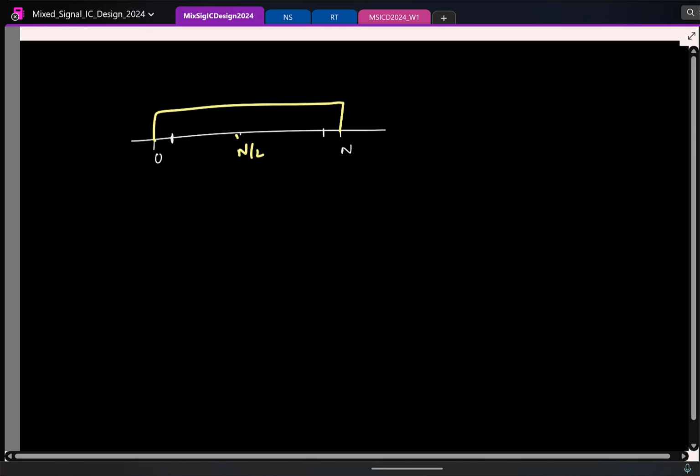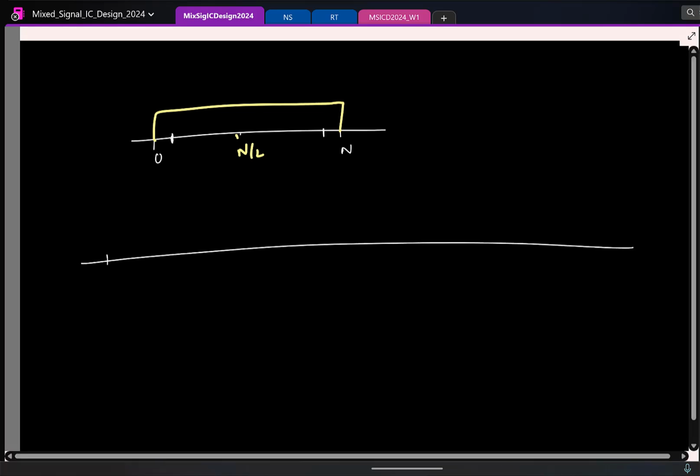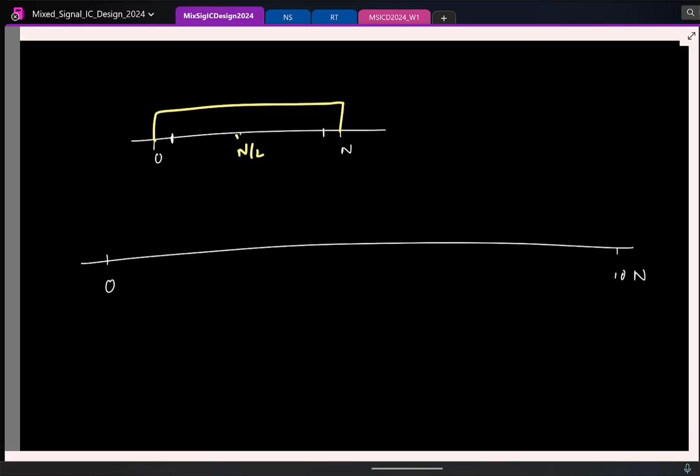So each signal is the same over all segments. No, you're trying to measure the power spectral density of a random signal, right? So you capture it for, let us say, 10 endpoints. Although you're taking an endpoints sequence and finding its Fourier transform, you capture it for a much longer duration and then do this. That's what it is.